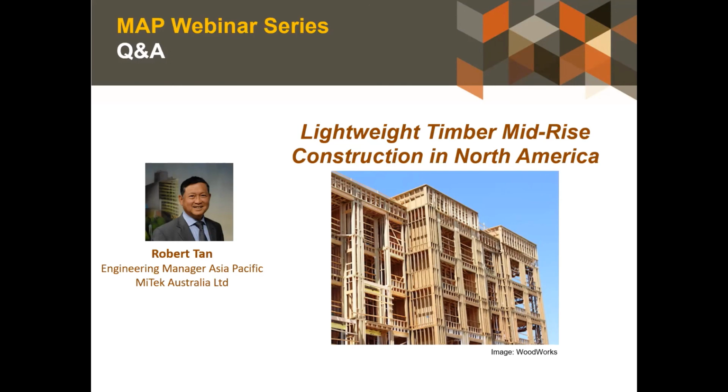One from Lynn, again, going back to the concrete. Does the concrete topping need extra formwork support, or just the floor studs would do the job? No, they use the bottom plate. The concrete topping is only quite thin. Those are non-structural concrete topping. As I say, they were predominantly lightweight concrete, and in some cases with those little polystyrene things or whatever they use. But these were non-structural. The ones that I showed you on research at the University of British Columbia, they are structural.